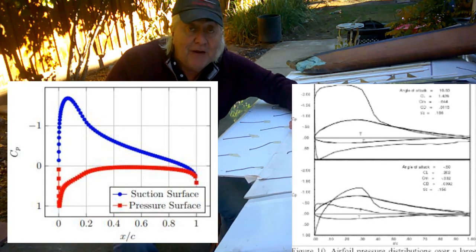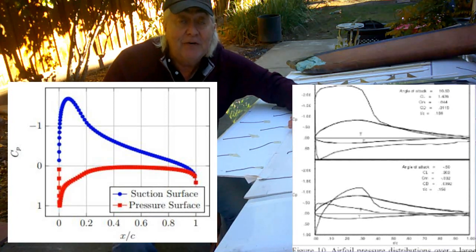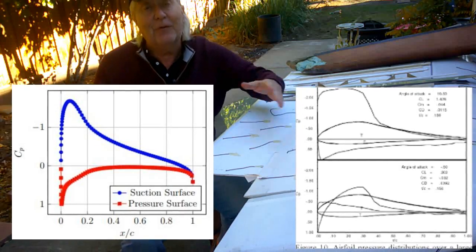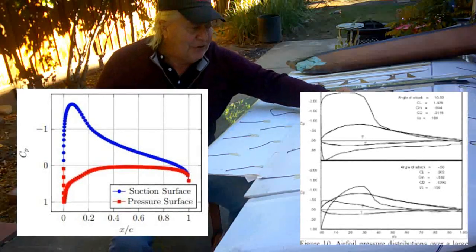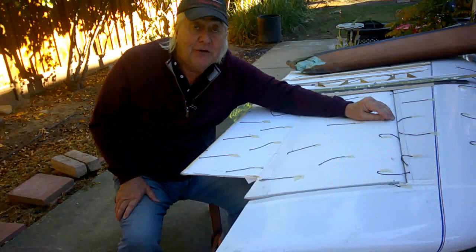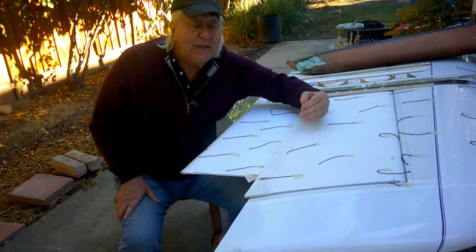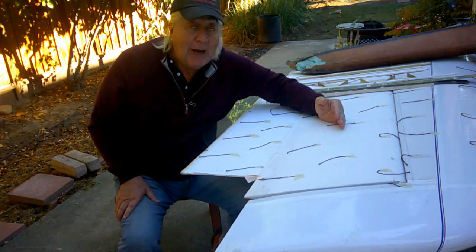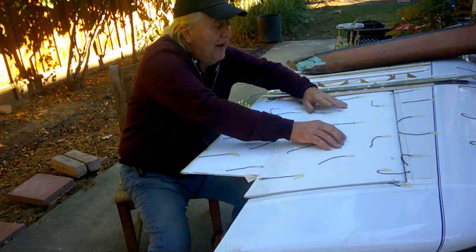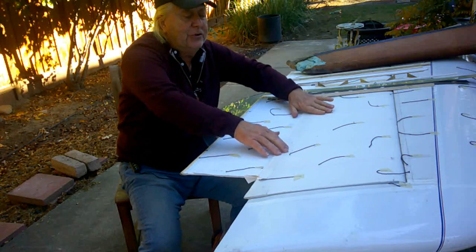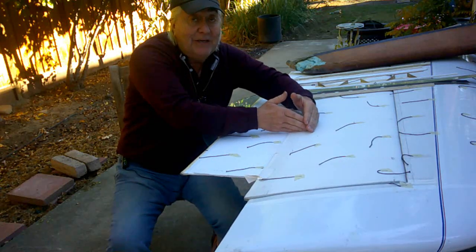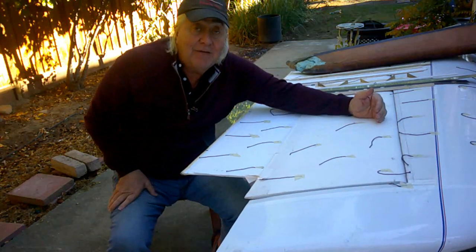And if you don't have enough energy in the boundary layer, you'll never get there, and you'll separate because of the Reynolds number issues. Well, the Reynolds number tells you when you're going to have an issue. So if you don't have enough energy in the boundary layer, if there's not enough inertia, the viscous forces and the pressure gradient are going to stop you from moving forward, and you're going to look for somewhere to go. You're going to try to get back to the trailing edge one way or another, but I got all of this higher pressure here in front of me stopping me from going, and I don't have enough energy to get there.